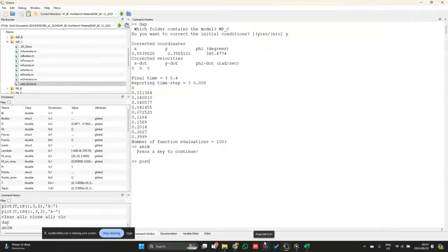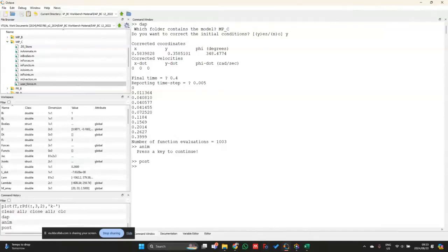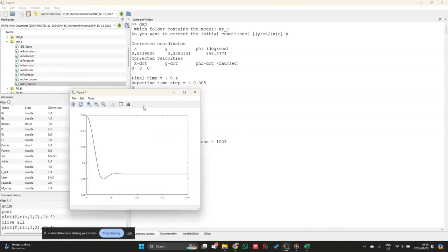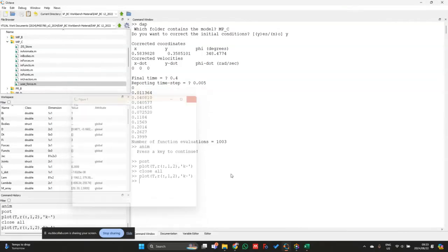Right, so then I'm just going to run post again, and I can once again go and plot the points. So I'm just going to type in plot and navigate to body 1 over here. Once again, I just have to close the animation pane. Okay, and we can once again see this relation over here, which looks the same as what we had for the previous 2 cases.